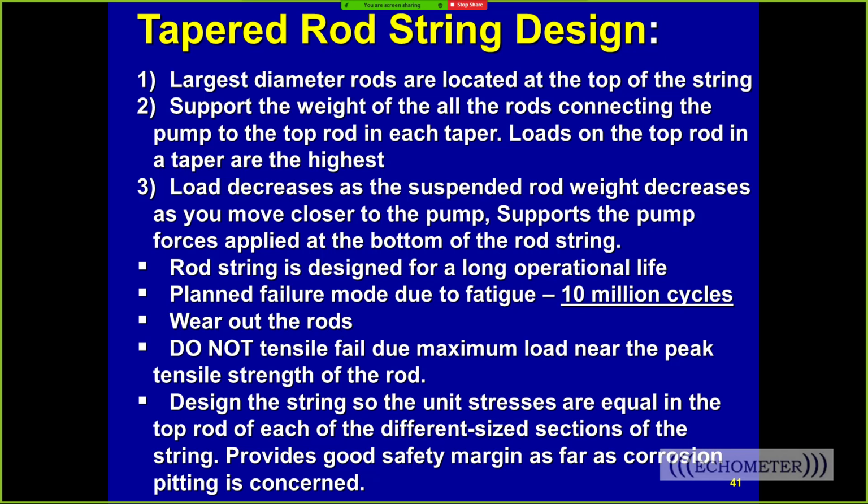When you say tight, what do you mean by that? A pump tagging down? No, we don't have... The tag is a mechanical force at the end or the beginning of the stroke, and you're tagging because there's a problem. The QRod will calculate the downhole stroke length, and it'll calculate the change in the stroke length if you change conditions, but it won't calculate the tag. I don't know of any program that'll calculate a tag. It'll calculate the change in the downhole stroke length, but it won't calculate a tag. No one does that.